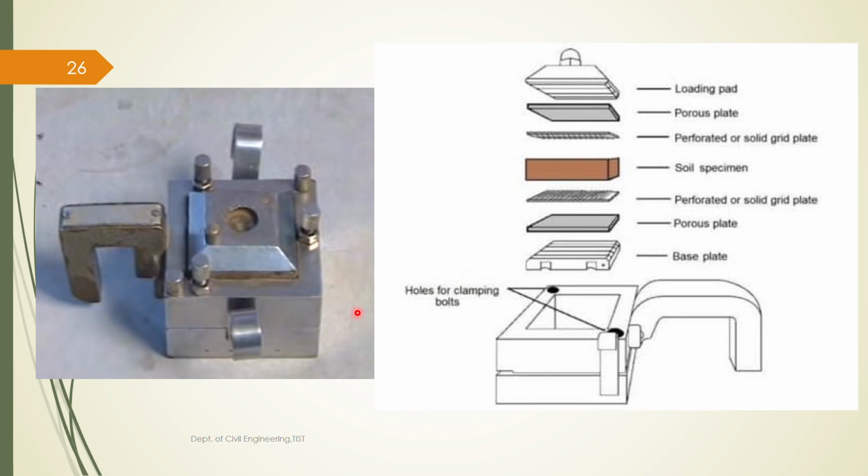Okay. Now shear deformation will be applied to the container in which the shear box is kept, and the proving ring will be connected to this inverted U frame. Fine. Now I told you that this setup is for undrained condition. If it is a drained condition, then you have to follow this order.